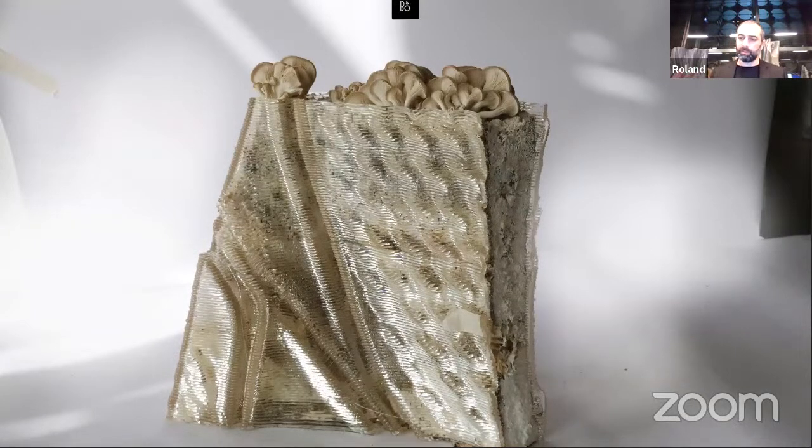And this is an attempt towards making an entirely biodegradable sandwich panel. A lot of the previous work I was showing is printing in virgin plastics, which we see as inherently problematic, but it's a step to a whole series of other processes. So this project is printed in entirely recycled plastic, which will then use fiber reinforcing, using flax fibers and natural fibers and bioresins to infuse those into place. And so the idea is working towards making something that's biodegradable.